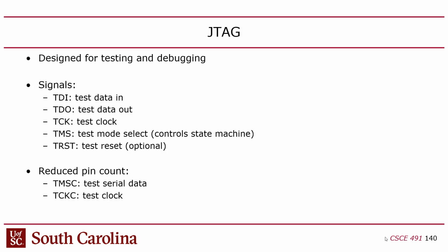So when I was in grad school, when we used to tape chips out, we would put holes on the top of the chip. We would put a hole in the oxide layer down to the top metal layer, and we actually had these micro positioners. So you'd have to look through a stereo microscope, and this had to be done on a vibration isolated table that floated on air. And then you'd have these micro positioners where you turn them and you'd position this little probe, and then you set it down on the chip, and you could directly probe a chip. But that's a real pain, and it requires very expensive infrastructure.